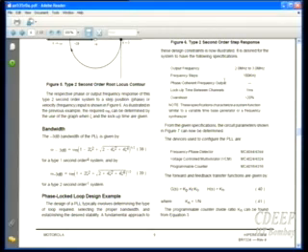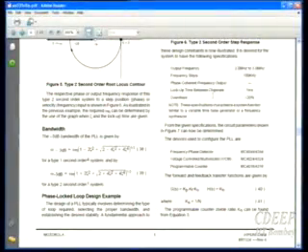Phase coherent means that we want to have zero error in the phase, so that the output phase and input phase are coherent. Means that they are exactly matched in phase. And then lock-up time between channels 1 millisecond. Means that if you change the frequency division ratio, then it should take a maximum of 1 millisecond so that again it will settle to the new frequency.